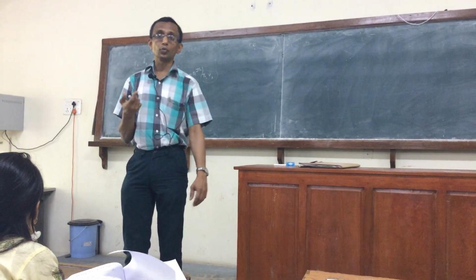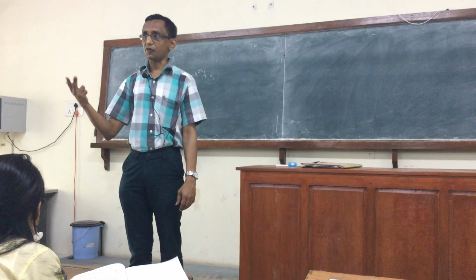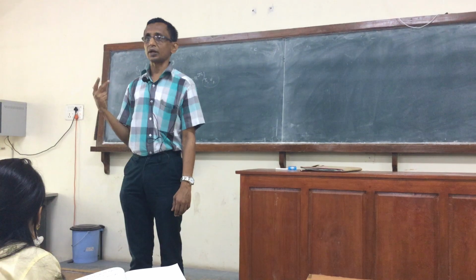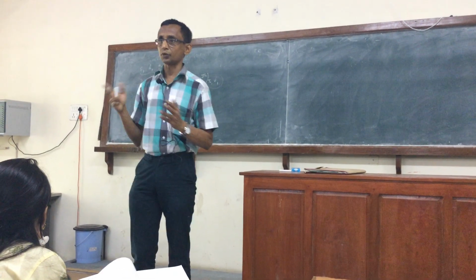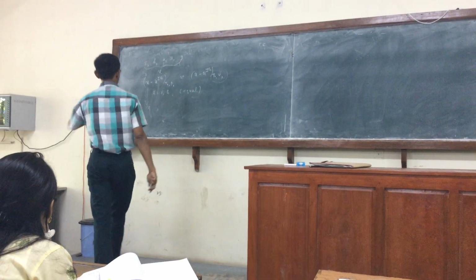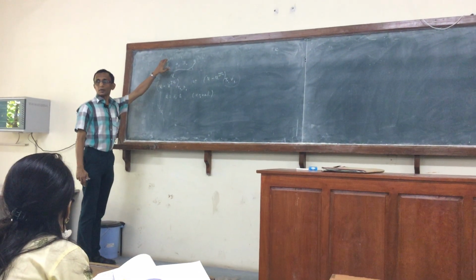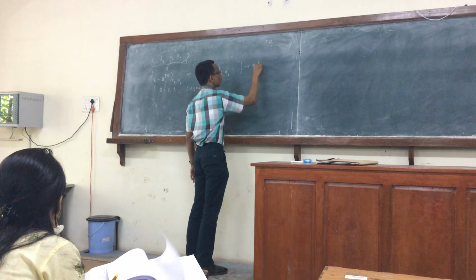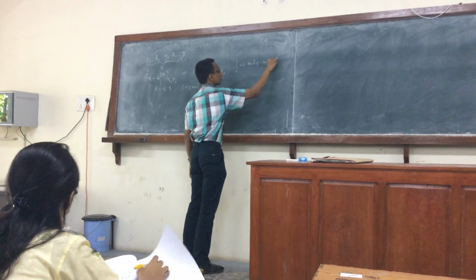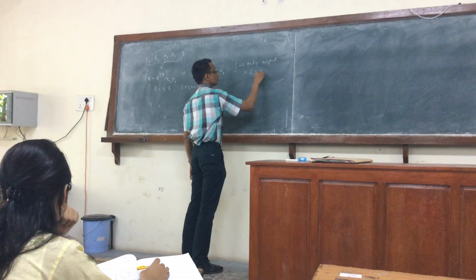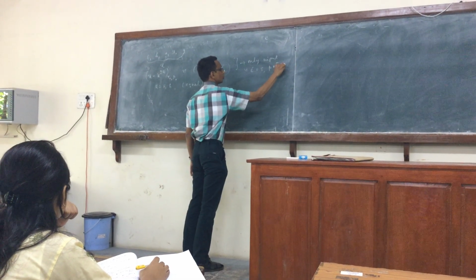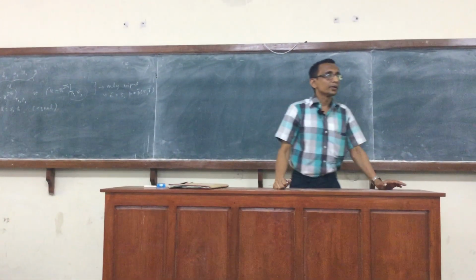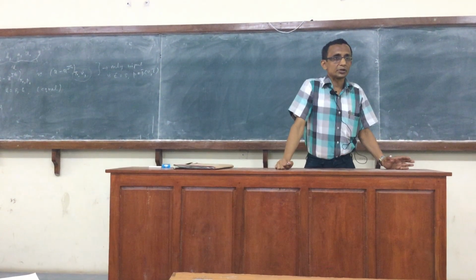So you have to verify that all of these departure functions can be calculated provided the equation of state is given. Formula might differ from one to another, right? But you can easily verify the only input to calculating these departure functions is the equation of state, which we assume is given to us in this form: pressure expressed as a function of the specific volume and temperature.